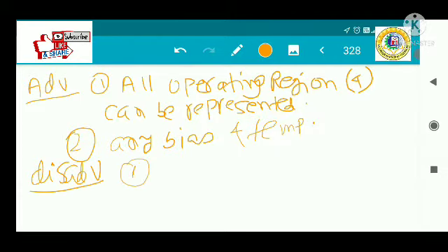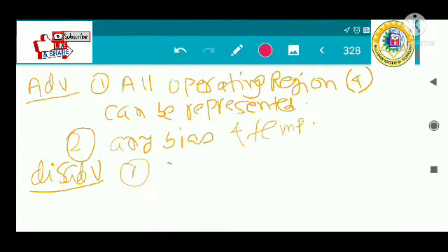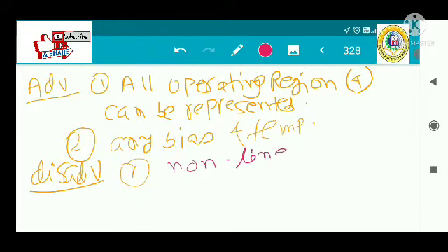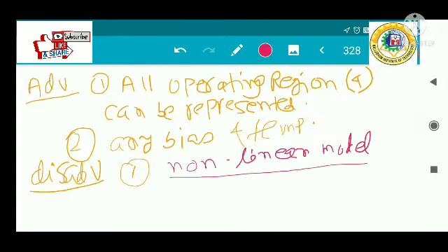there are two main disadvantages, and the main one is that it is a non-linear model. It is not a linear model. Why nonlinear? Because we are using a nonlinear device, that means the diode in there. So the superposition principle of linear circuit operation cannot be applied here, that means in network analysis you cannot apply superposition or bilateral linear network methods.